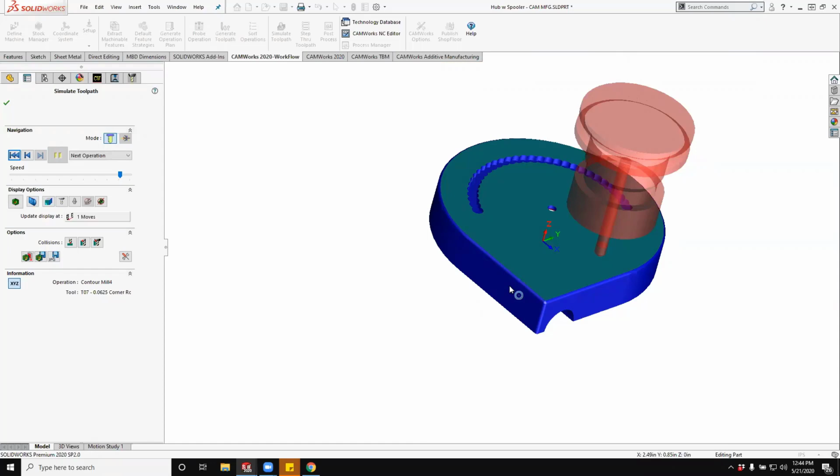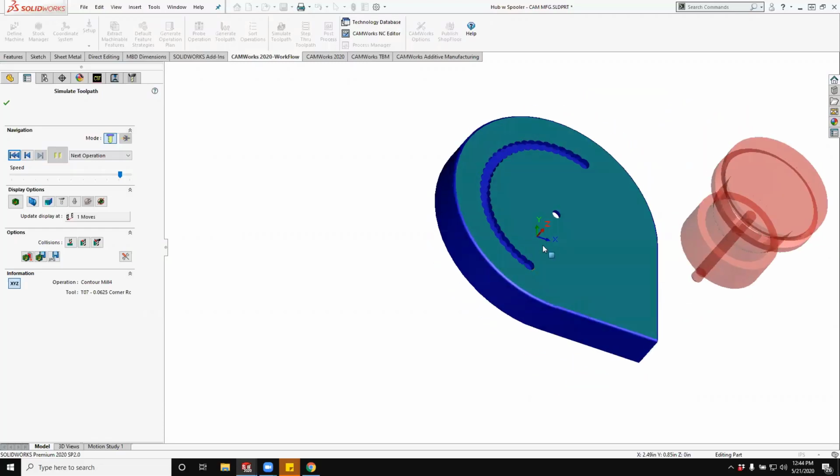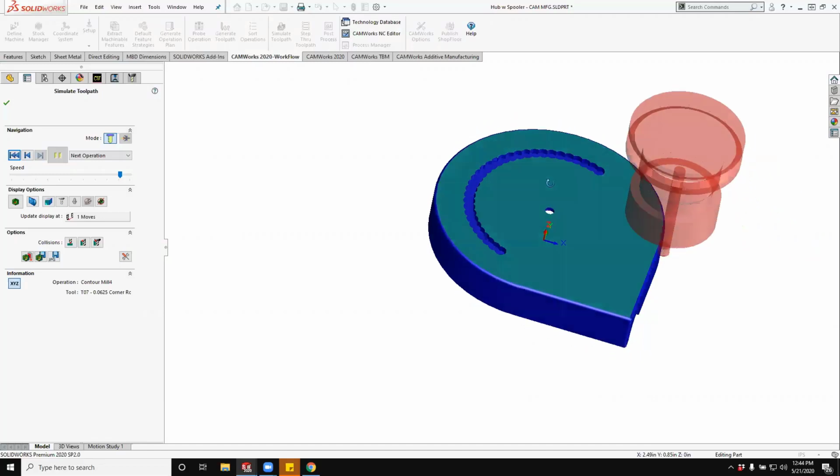So a 2.5 axis operation will still be generally run on a 3 axis mill. So you generally don't buy 2.5 axis mills. When we talk about axes, we talk about axes of movement. So we've got our Cartesian coordinate system here. We already said our x-axis is the side-to-side movement of the machine. The y-axis is the front-to-back movement of the machine. And the z-axis is the up and down movement of the machine.